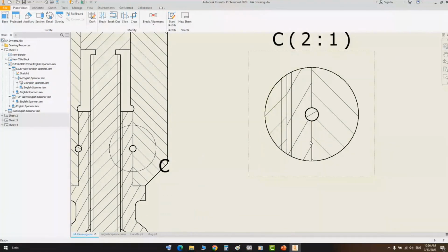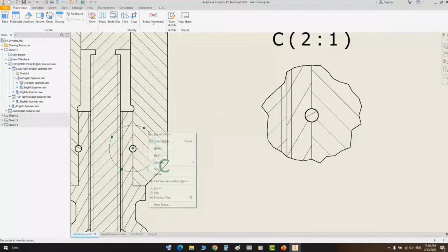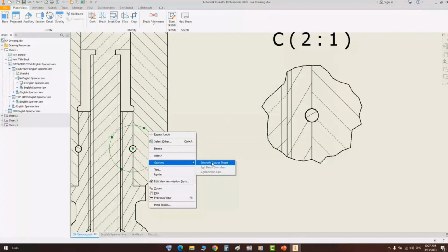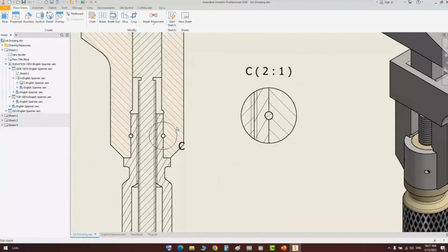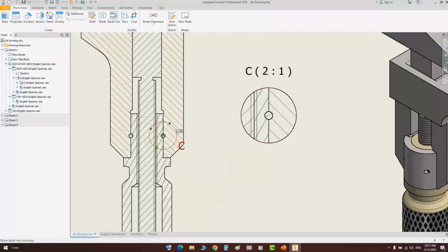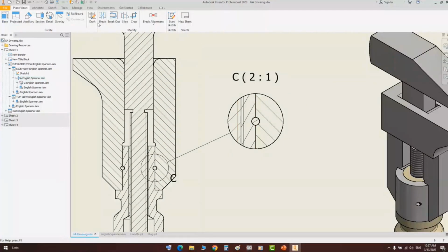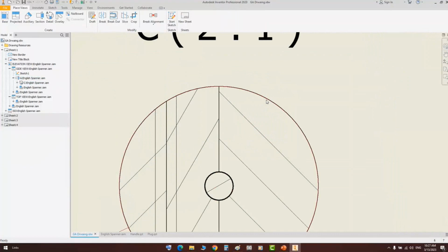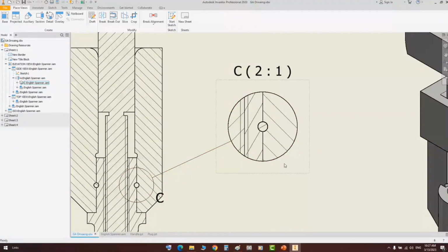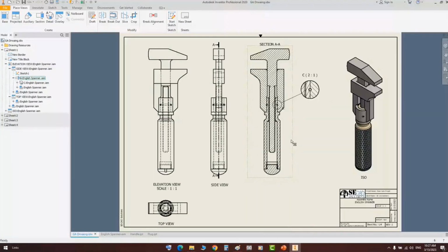So again, that's the rough cut. And if you would like to make it smooth, from options, select the cut view from here and select smooth cut shape. And you can change that shape to a full detail boundary. So from the full detail boundary, you can make a connect line like that. And for the detail boundary itself, you can change the style of this line. We will discuss how to control the styles in the next minutes, inshallah.